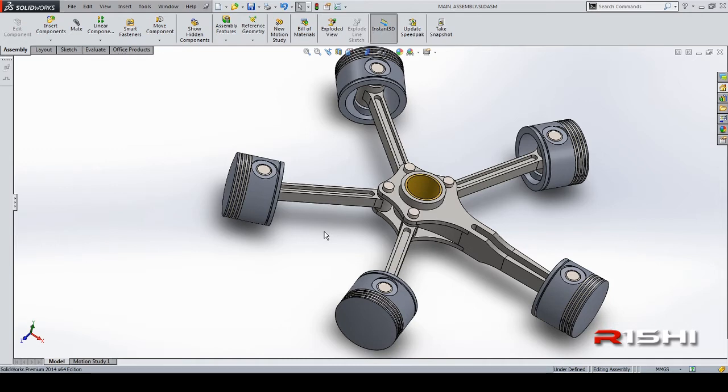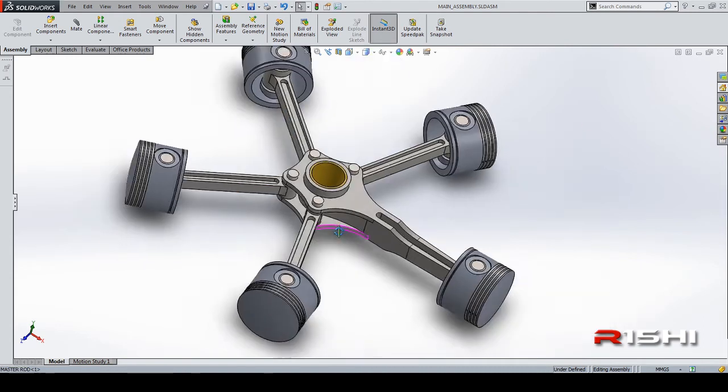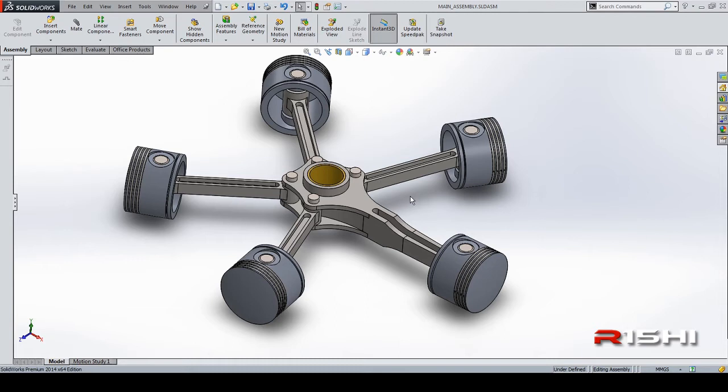So before creating the final assembly right away, we will create a subassembly of this articulated rod. Once that is done, we will start creating a main assembly where we will upload the master rod as our main part and then the subassemblies of this articulated rod. This way it will save a lot of time assembling these individual parts on every repetition. So let's start creating the articulated rod assembly now.